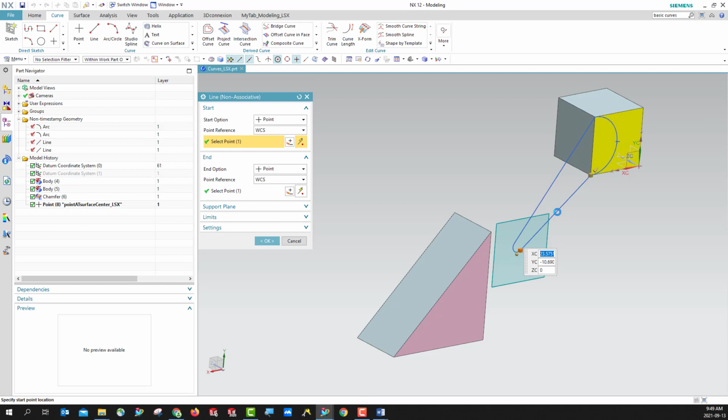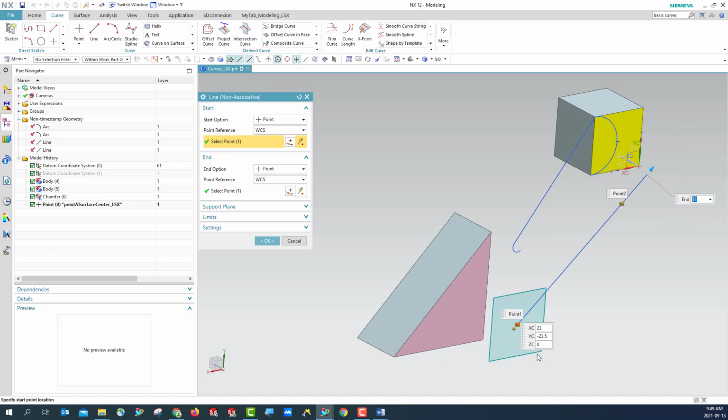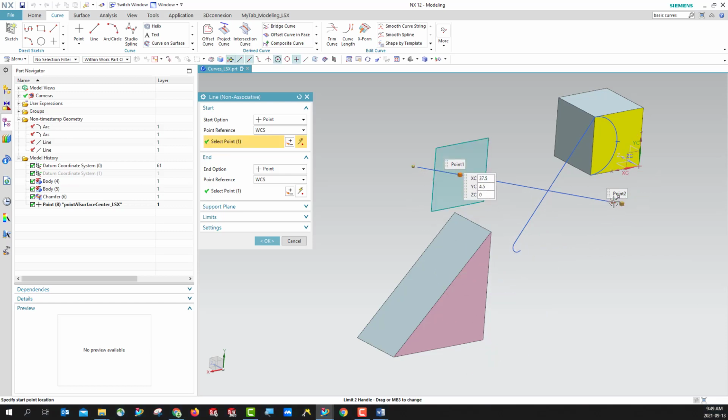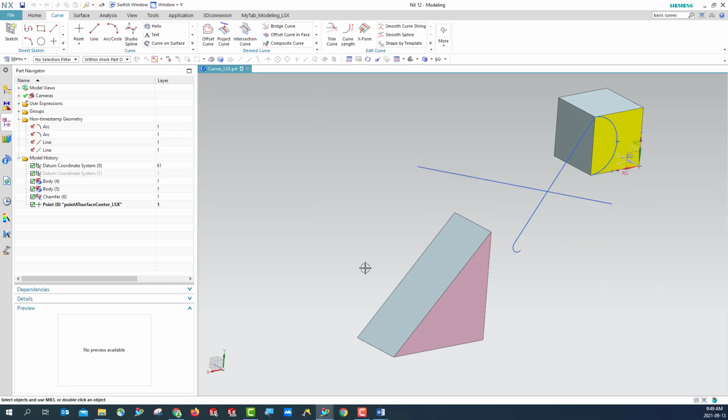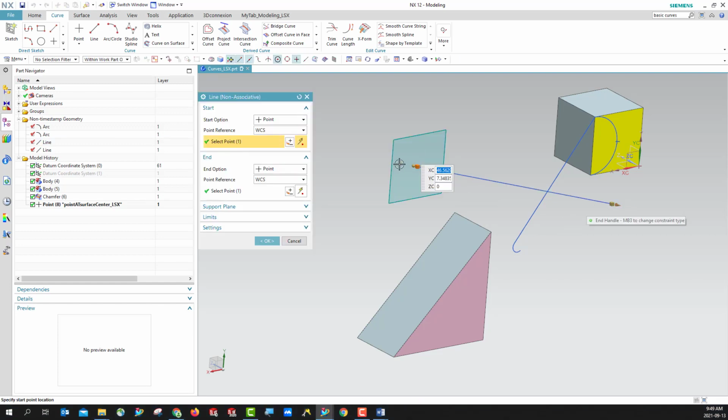So what we can do here, we can double click these curves, and then we can manipulate those handles for its orientation. And here's the starting point. This can help us modify its length, and this one can help us manipulate its orientation. If you accept, then it changes. If you double click again, you can see the handle changes as well. So you can also change its parameter, the length, using this toolbar, the cone or the sphere, or change its orientation using these two handles.